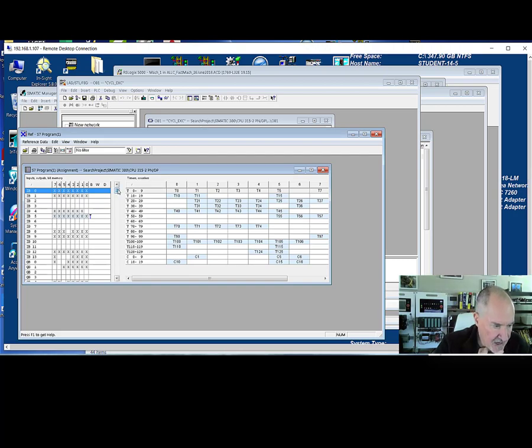So you can see here, and I have no filter on this, so you can see the inputs listed here, you can see the outputs listed here. And what you see out here to the right is that some of these things were addressed not as individual bits where these X's are shown, but as whole words or bytes, right? So these MBs, you can see here this is a memory word. This would be known as memory word 2.